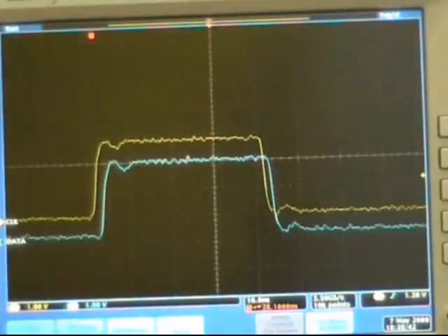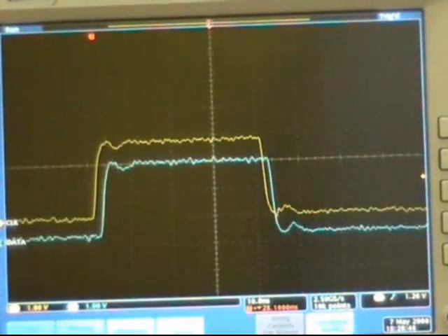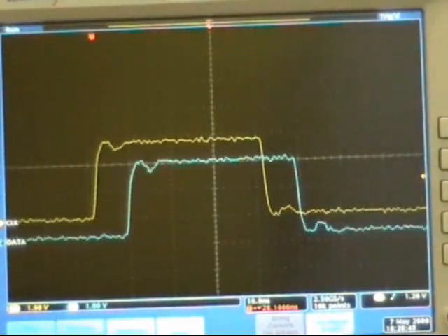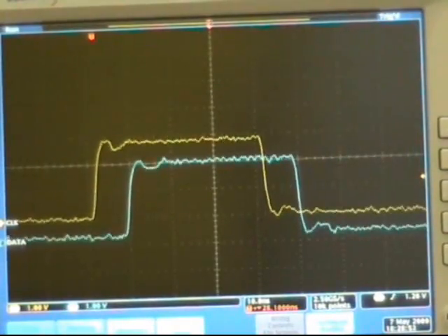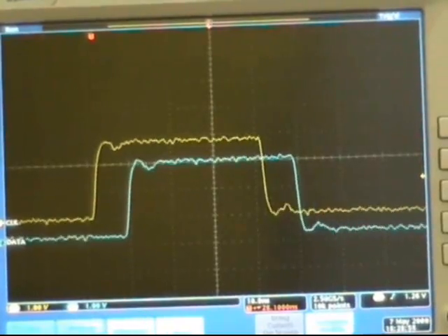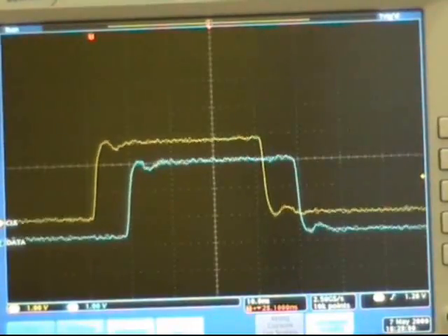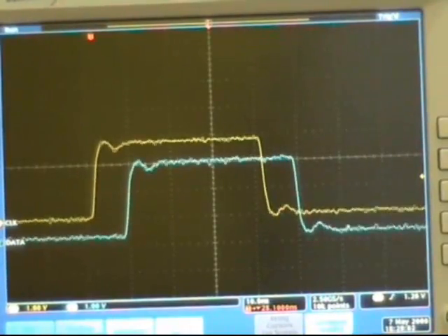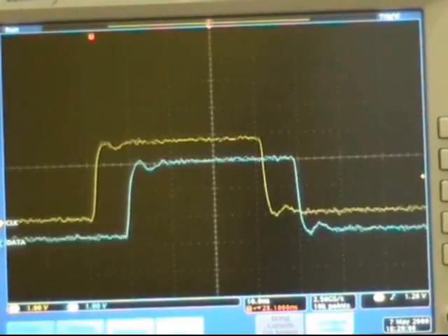Once I program the software, you can see the blue color curve moving further to the right. And in fact, measurement on the oscilloscope will confirm that the delta time difference between the yellow color curve and the blue color curve is 8 nanoseconds. This showcases the capability of the I/O module in terms of its flexible edge programming.